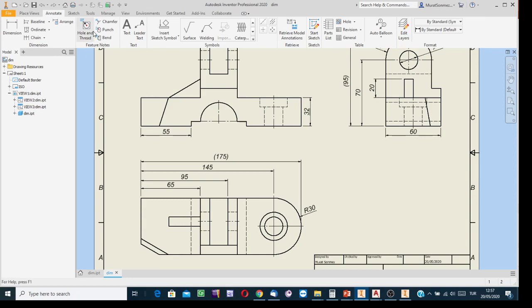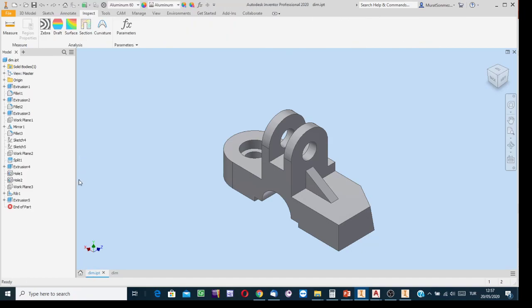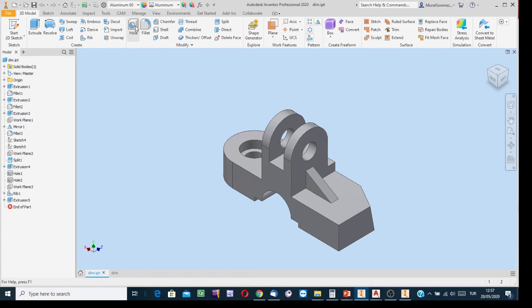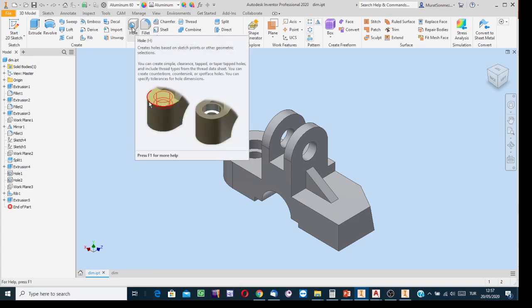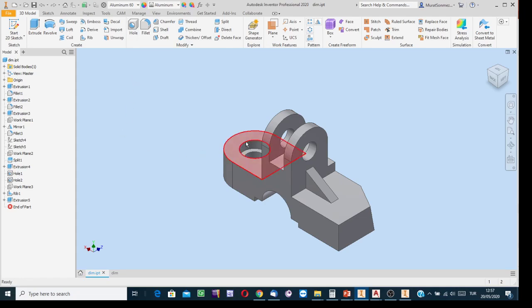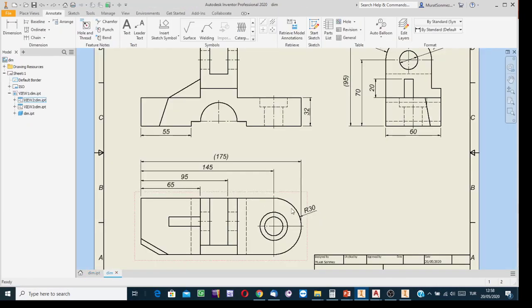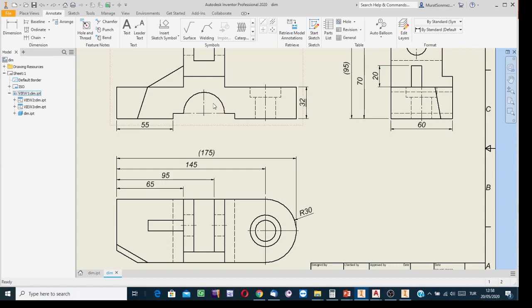And then let's see the things in a shorter way. In Inventor, there is such a tool. If sure that hole has been created applying the hole process, you see here, I have the hole icon. Using the hole creation tool, here is the push button for that facility. Created the counter bore hole, and that's its icon. If the hole has been created, not applying extrusion but applying the hole creation process, then yes, at the dimensions stage, sure, there is a convenience.